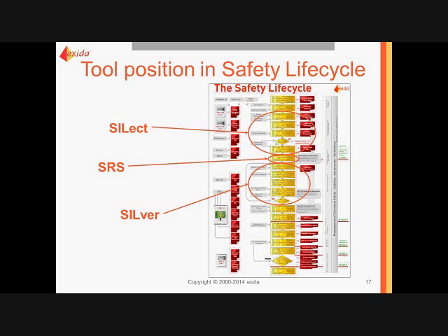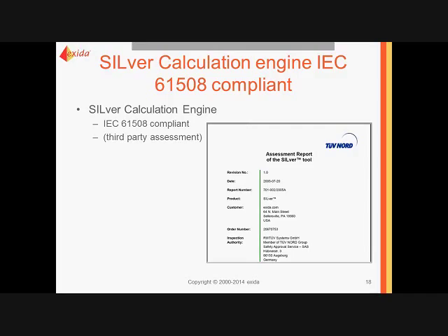And then you have the SIL tool, which enables you to go through and do the SIL verification. The SIL calculation engine is IEC 61508 compliant. This was actually assessed by a third party and was given compliance to 61508.